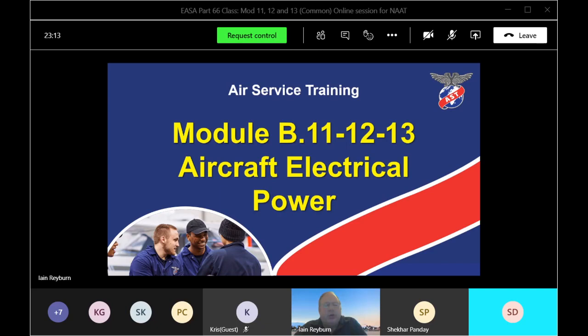This is where we finished off on Friday. We talked about the bus power control unit. That is the electrical brain for the whole of the aircraft. So again, it's looking after every electrical component in the distribution system of the whole aircraft, apart from the generator control units, which control their own generator. But the GCU always tells the bus power control unit the state of the output of a generator, or if it has failed, because it needs to know.